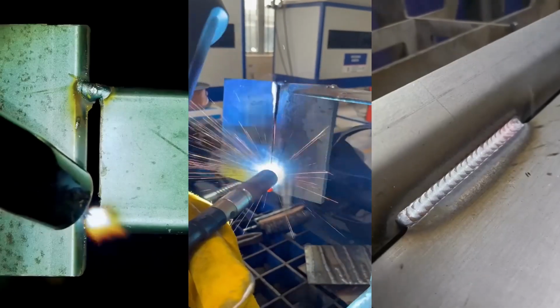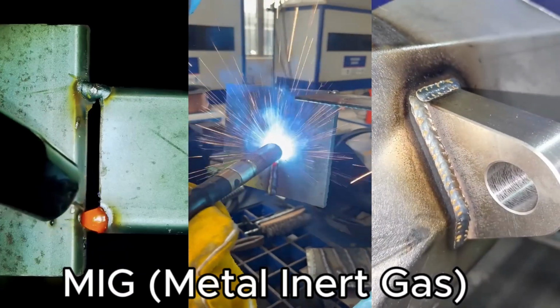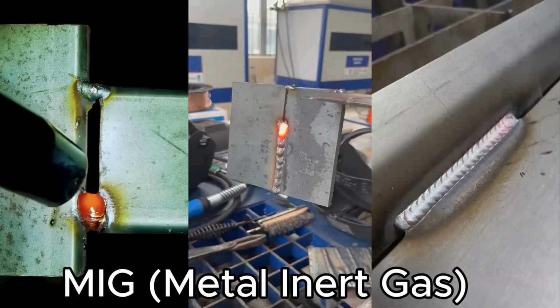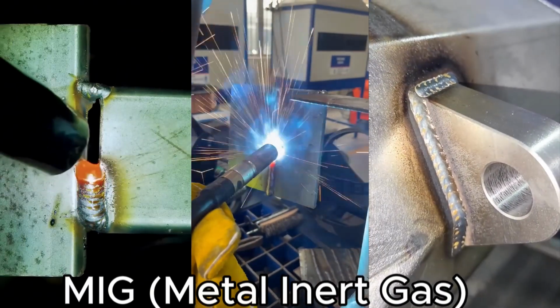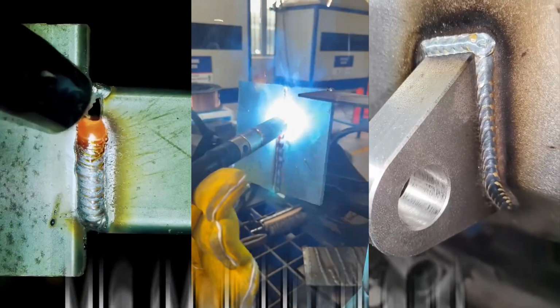Let's start with MIG welding, or metal inert gas welding. It's one of the most common types in industrial use. In this process, a wire electrode is continuously fed through the welding gun, while a shielding gas, like argon or CO2, protects the weld from contamination. MIG is fast, efficient, and relatively easy to learn, making it ideal for automotive and structural work.